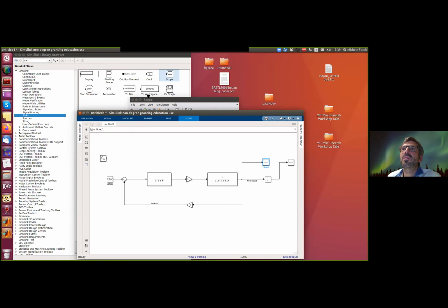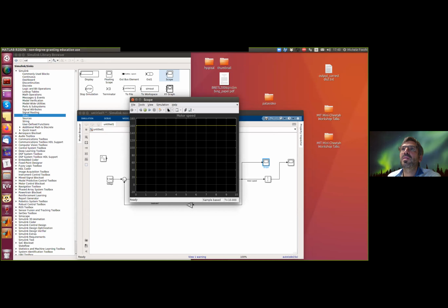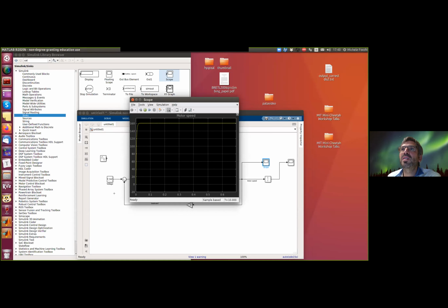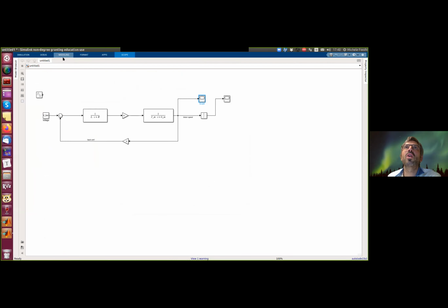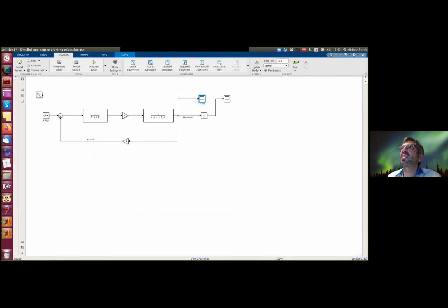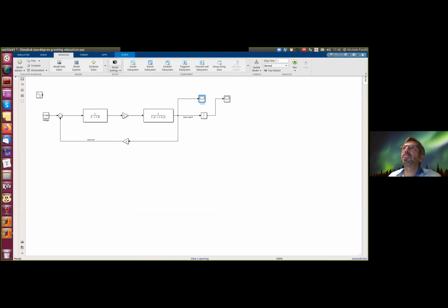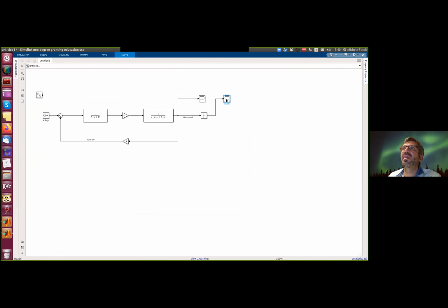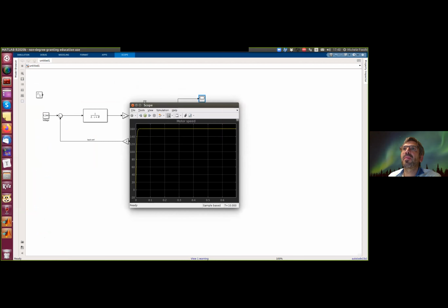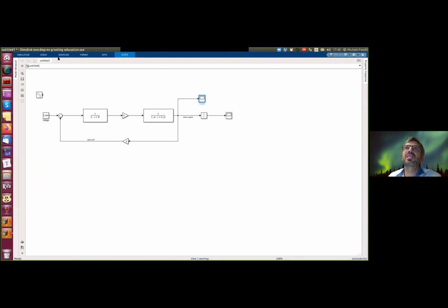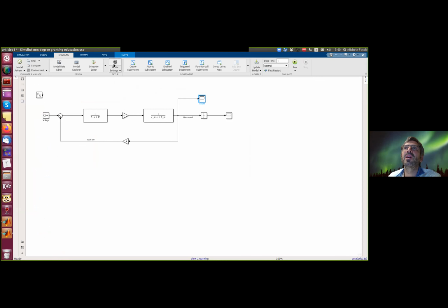So this is a plot of the speed. You cannot see much, so it means that the simulation is too long for the electrical dynamics you're trying to see. So you can change the stop time to, for example, 1 to magnify this effect, which is the starting up.